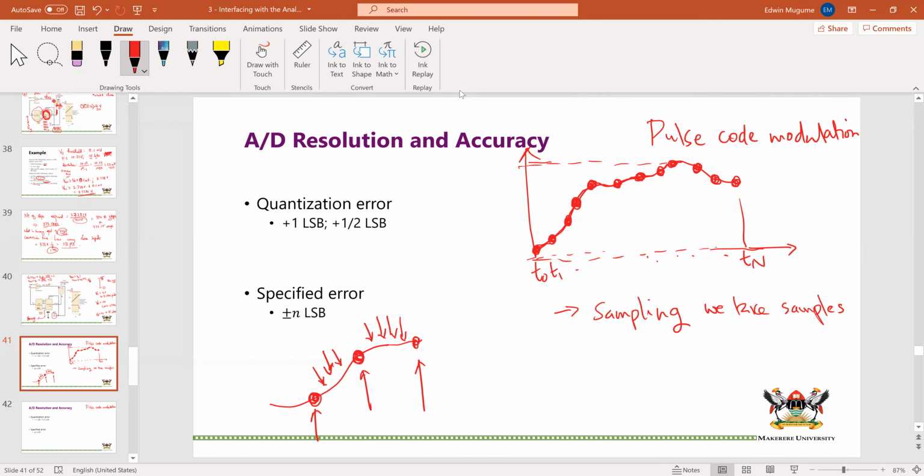In other words, if I take these digital values, there'll be enough for me to have captured enough to reconstruct the signal or to decode the signal, understand what it was about. Okay, so this is the process of sampling. We don't need to know the whole signal. We just take samples at specific intervals in time.